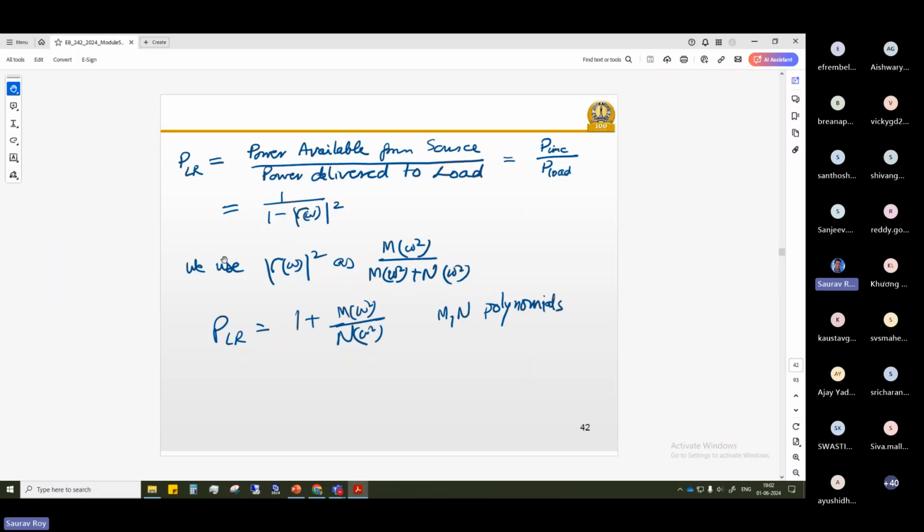You should not write return loss as minus 10 dB. You should write return loss as 10 dB only. Similarly, insertion loss as 30 dB. You cannot write insertion loss as minus 30 dB. That means it's actually gain. Okay, that you should remember. This is a very subtle difference in terminology. These loss parameters, whenever you define, should not come with a minus sign.